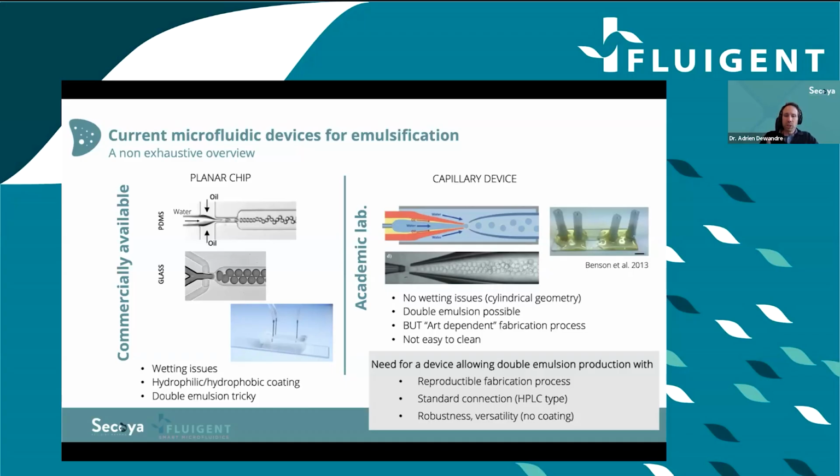And to prevent these wetting issues, you need to apply coatings on the channels, hydrophilic or hydrophobic, depending on water in oil or oil in water emulsion. The drawback of these surface treatments is that they are not robust. With the formulation I tested at the time, the hydrophobic coating resisted approximately 20 minutes,